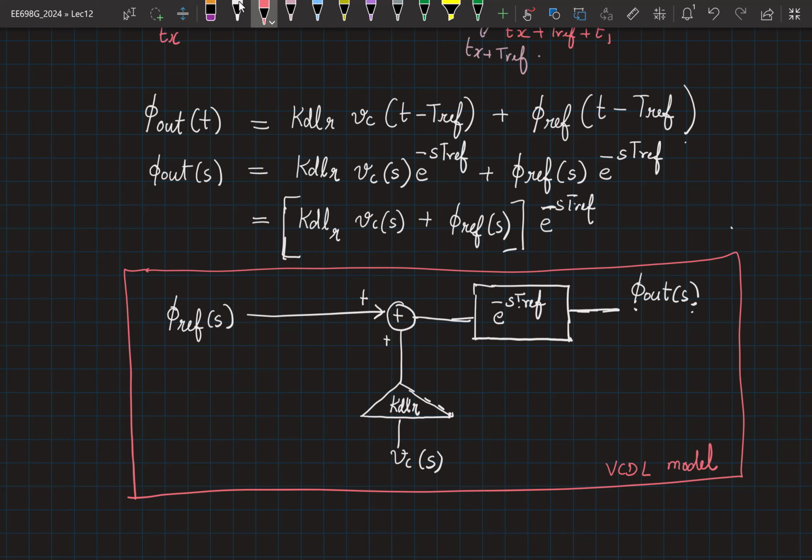Because right now we are working with a rough idea. If I increase the charge pump current, I know that the loop is likely to lock faster. But by how much faster is it going to lock? We are engineers. We want to be able to give quantitative numbers for everything. So that is the aim: a theoretical analysis of the DLL, which will help us design a better DLL. Take a minute, feel free to discuss, and see if you have any questions on this model.